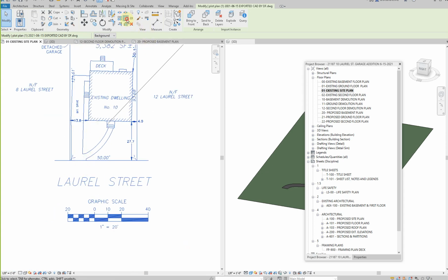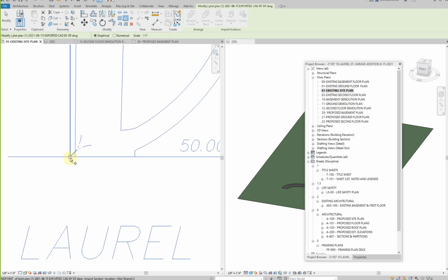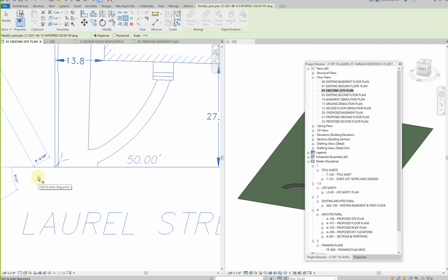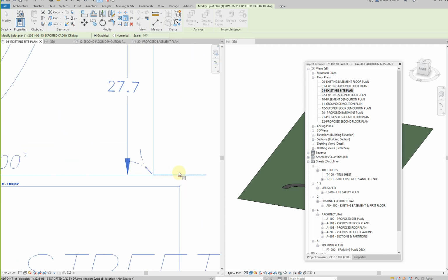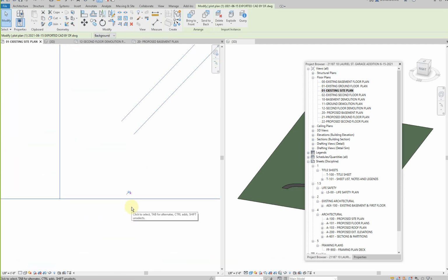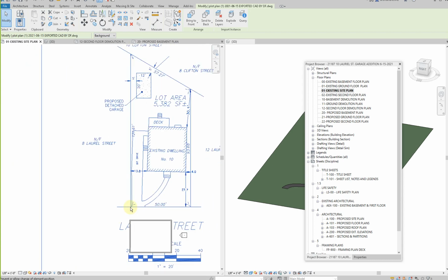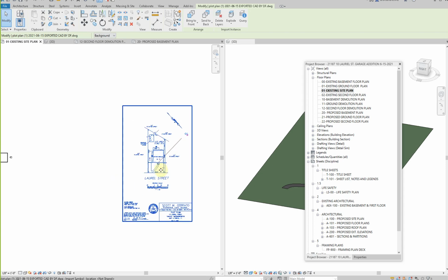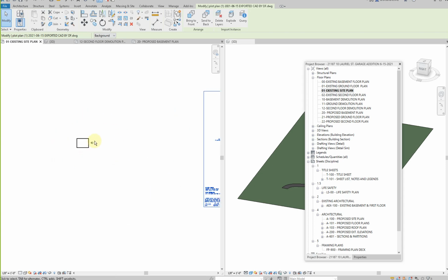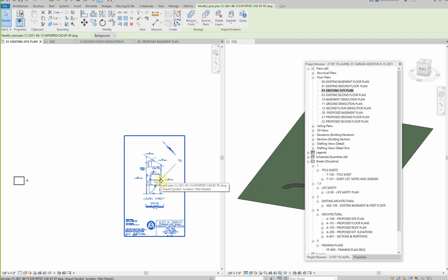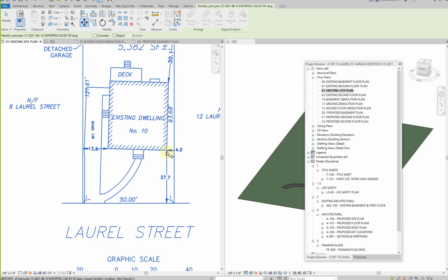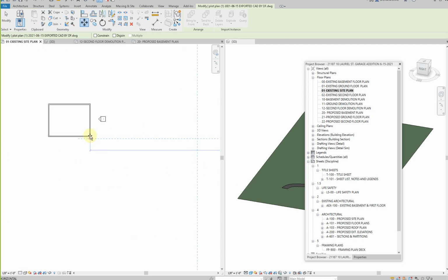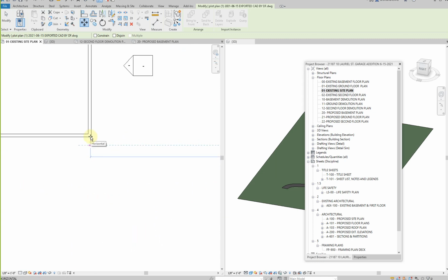And we're gonna do the scale again. So we go here. By the way, these little things indicate where the property corners are. That's what that means, property boundaries. All right, so we go here, we have that guy there, perfect. So what do I do with it? Because our Revit model is set up around this element, I like to grab this and set it up so that it's around that element. All right, close enough, because then everything's gonna be centered around that.